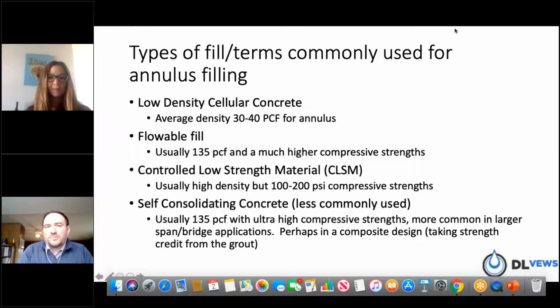And then on some of these larger span bridge jobs, long span, like 20-foot plate style bridge jobs with very low cover amounts, I've seen self-consolidating concrete used as well, which once again is very heavy. So we have to be cautious of the buoyancy forces being put on the liner pipe. But it is something I see being specified very seldom for those larger jobs. Okay.